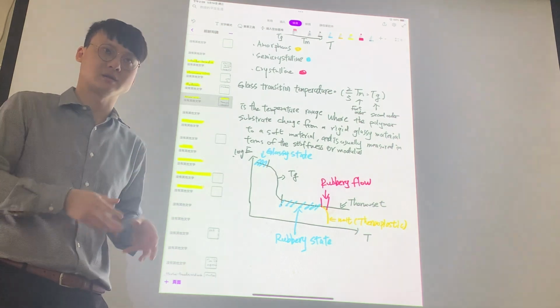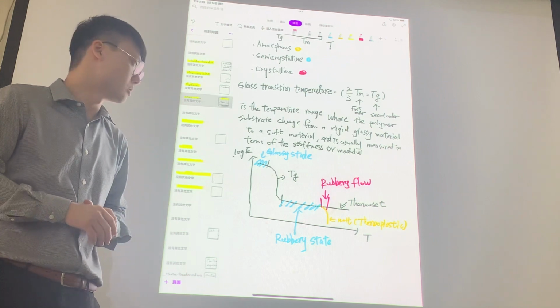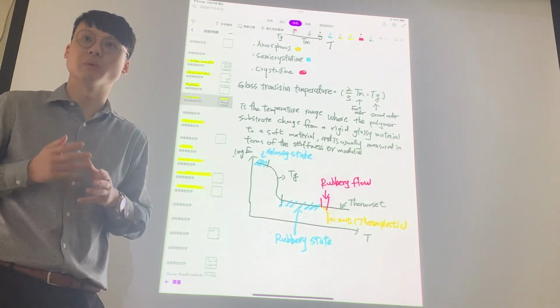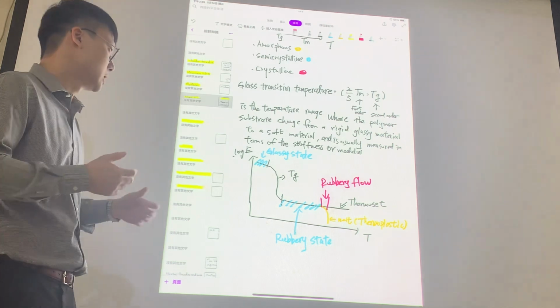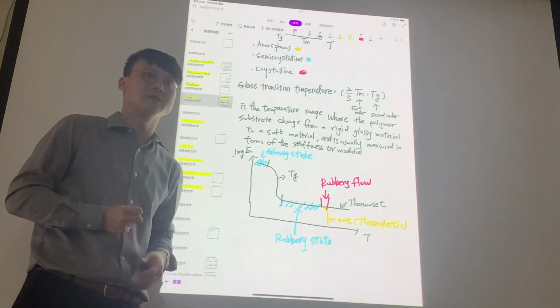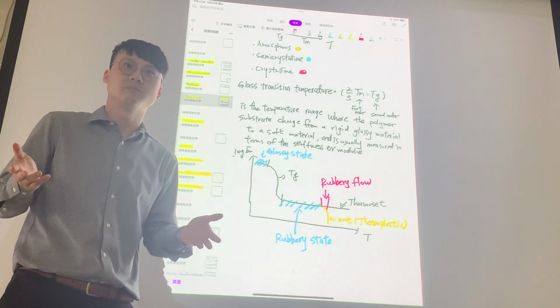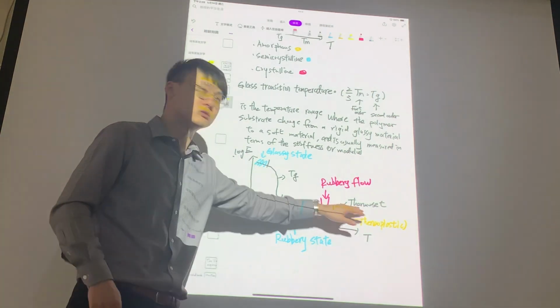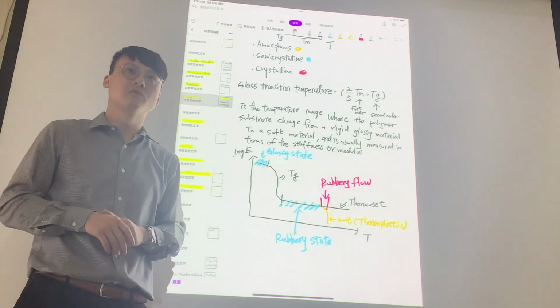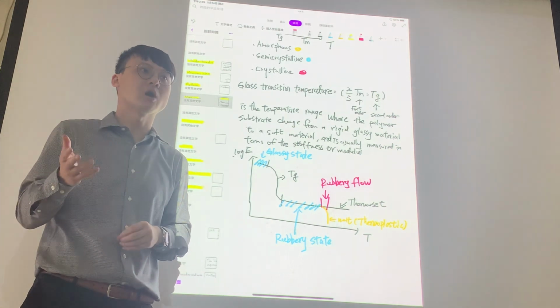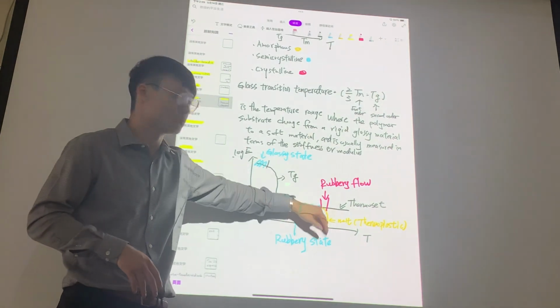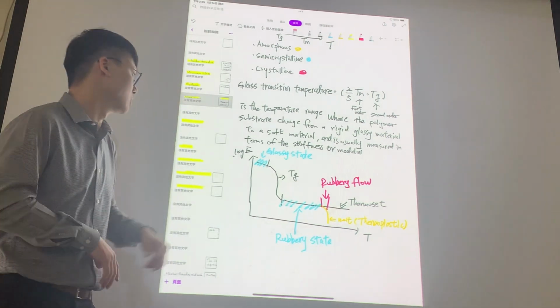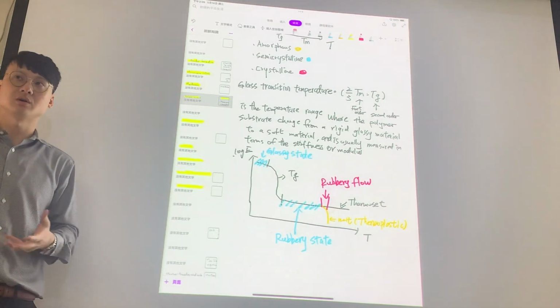However, thermoset is all amorphous. When we deal with amorphous, there is no melting point. Think about epoxy: under this curve there's no melting temperature, meaning the curve continues on. Now for thermoplastic, if we're talking about semi-crystalline materials, then there is a melting point and the curve goes down, so the modulus changes.